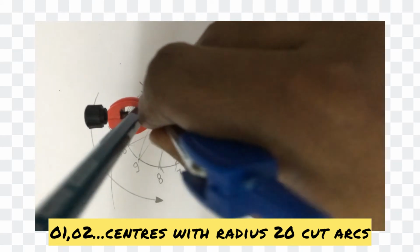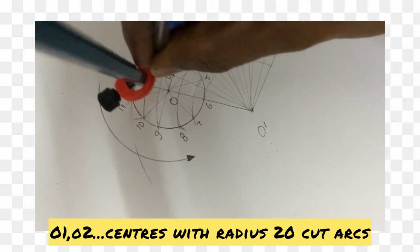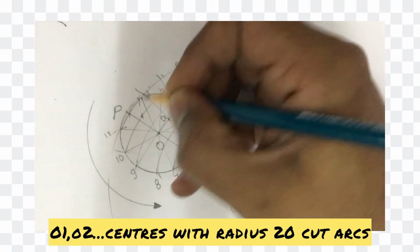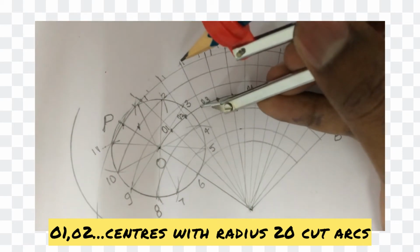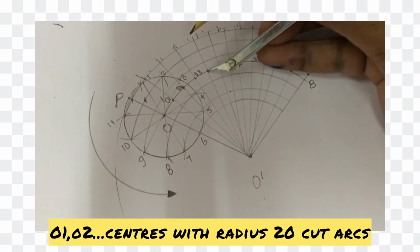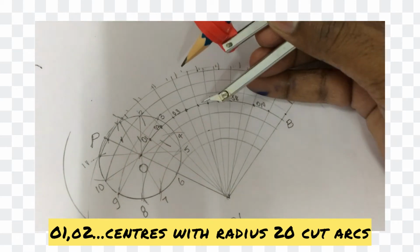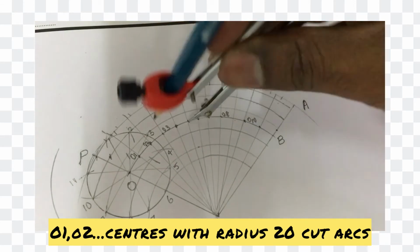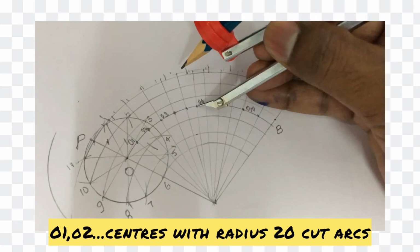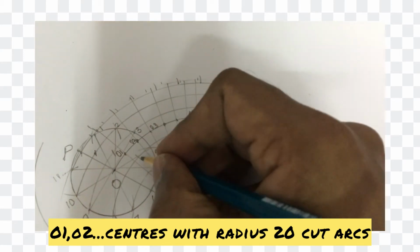So go to O2 position upon the rotation in the anti-clockwise direction. So your circle gives movement to till here. So these are the points of intersections. If you see, you got 1 point of intersection along this 2 and this. Later O3 is a point and cut the third line, and O4, hope you are getting, whereas in epicycloid you are going to get curves outside the circle. As it is a hypocycloid, you will be getting arcs inside. So this is O5 and this next O6. Please make sure to write the letters and numbers in order not to confuse.